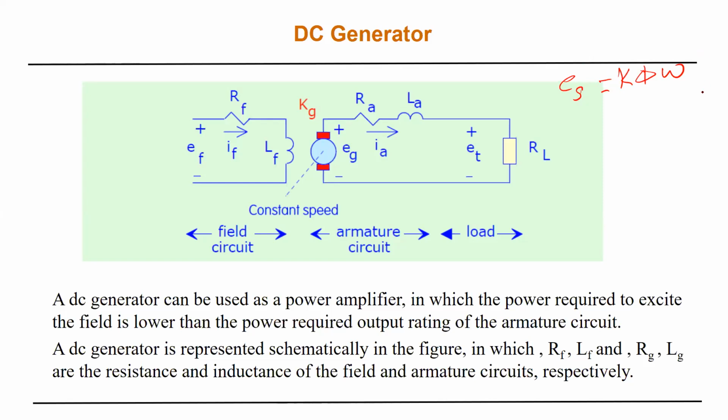In the generator, we take omega to be constant. Remember, before we have the back EMF, VB, equal to, again, K, phi, omega, where we take in the motor side the field is constant. Because field is also proportional to the currents. Yes. Current. So in here now, I'm converting the mechanical, which is omega, into the electrical, while in the motor, I'm converting the voltage into motion.